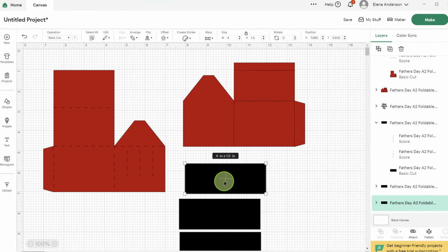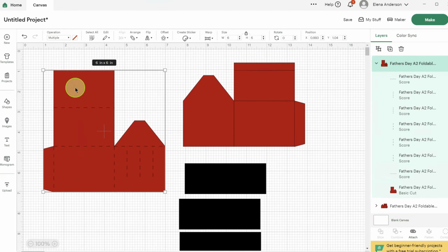And after you've done that, what you want to do is click attach, grab the whole group, and you can check because the top of the group will be highlighted in blue and you'll see the 3 pieces under it, or the many pieces under it if it's this group, for example. And you click attach. You have to do that because attach is what tells the software to tell the machine to keep those lines exactly where they are now on the piece that's being cut.